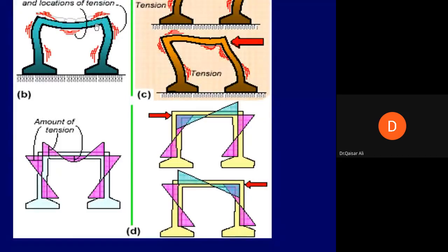However, now in the case of earthquake analysis, you have an additional bending moment. If you look at this figure, you have an additional bending moment on the bottom side of the beam. The structure must be designed for this bending moment. And this bending moment will give you some reinforcement, and that reinforcement shall be placed here on the bottom side of the beam, which was not the case in a frame analyzed only for gravity load.